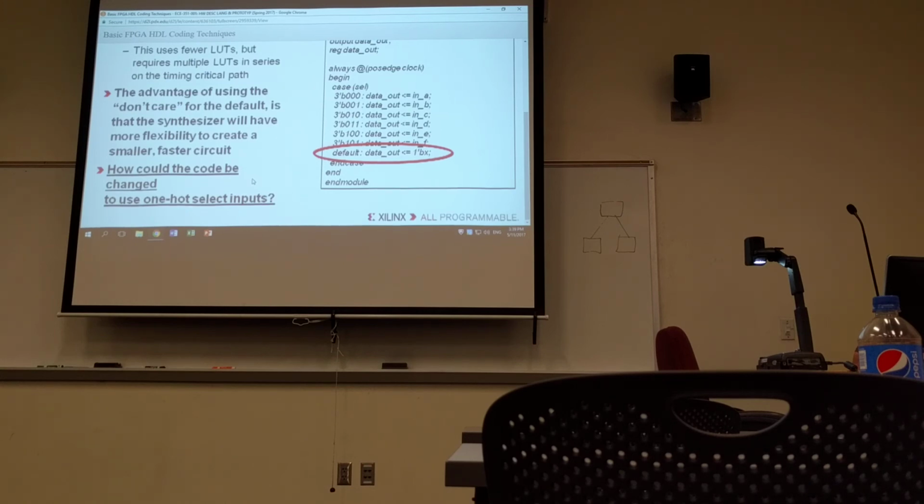This design also inferred a register on the data out signal. This effectively added a pipeline stage. Recall that this is one of the best ways to improve system performance in an FPGA. If this did not have a registered output, a critical path could evolve through the...